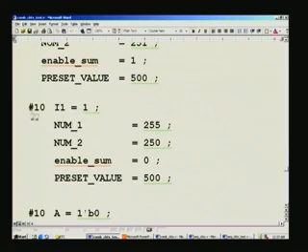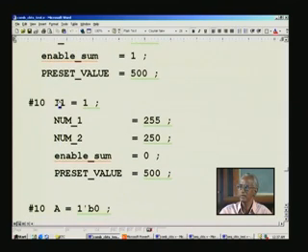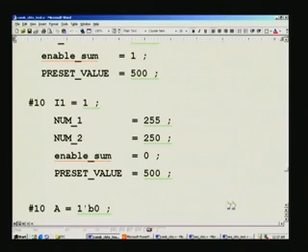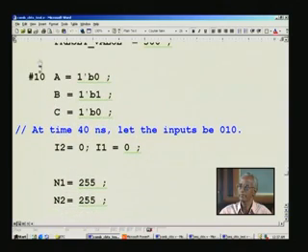So once again after 10, this is cumulative, so now I think we are at 20 nanoseconds. So you have to unfortunately keep track, but you can always keep track by keying it as a comment here. That is why I had put it at many places, and once again all the inputs. Mind you, the stimulus is only for inputs. You need to only apply inputs as such, right. The simulator will give you everything in one shot as a waveform, both inputs as well as outputs. So you can see that comment here. So I have kept track, right.